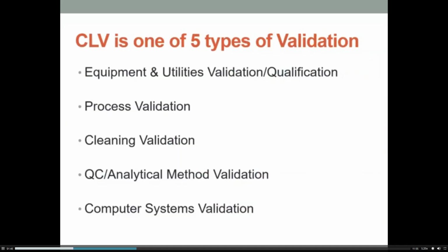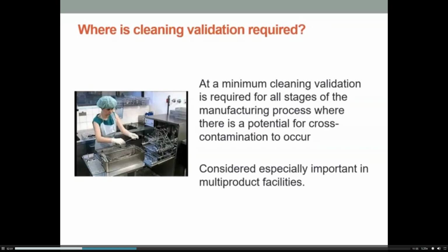Cleaning validation is one of 5 types of validation. There is equipment, utilities validation or qualification, process validation, cleaning validation, QC and analytical method validation, and computer systems validation. Where is cleaning validation required? At a minimum, cleaning validation is required for all stages of the manufacturing process where there is a potential for cross-contamination to occur. It's considered especially important in a multi-product facility where there are a number of products being manufactured.